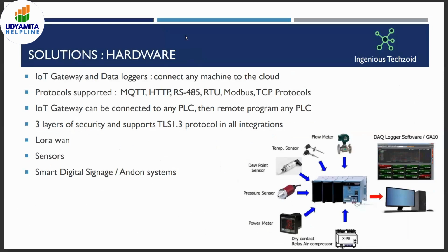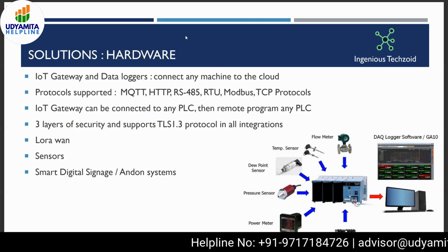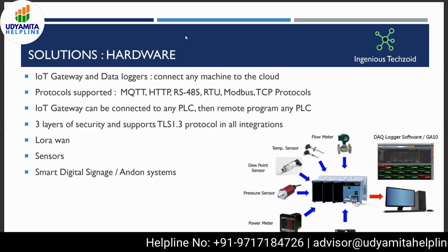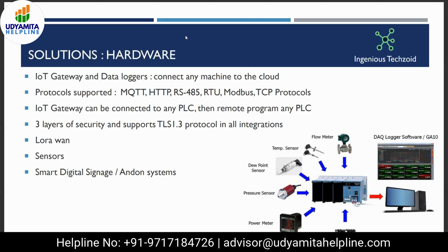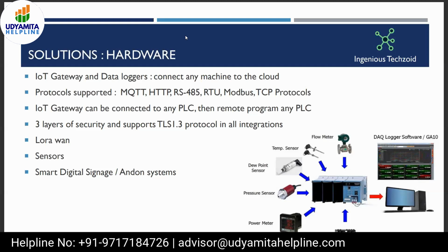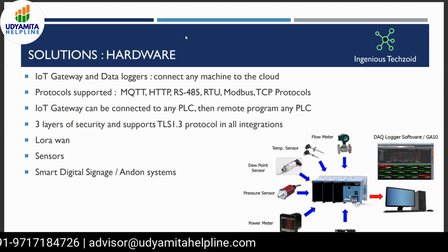We have IoT gateways or data loggers that can connect with any kind of machines. Our hardware supports all these protocols like Modbus, RTU, RS485, MQTT, and HTTP. You can connect with any kind of PLCs like Allen Bradley, Siemens, Mitsubishi, Omron, or any other PLC. And it supports the TLS 1.3 protocol, so it will give you completely secured communication.